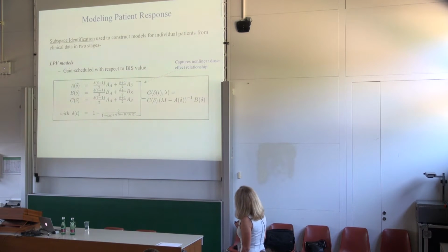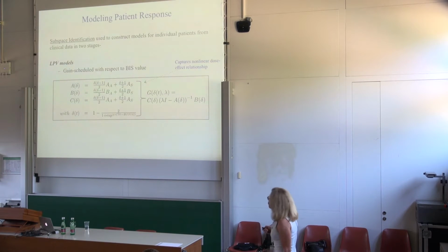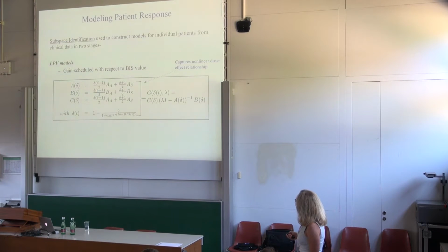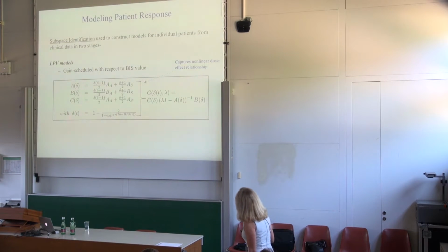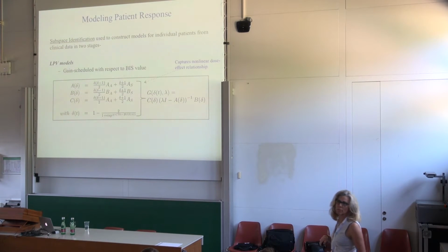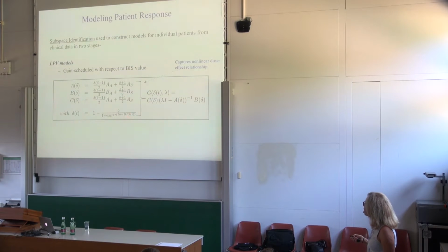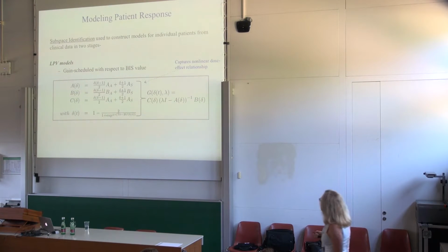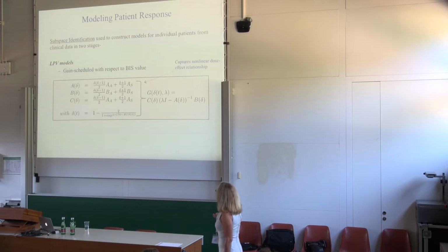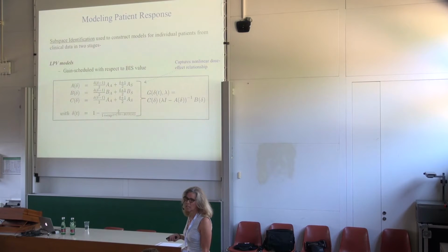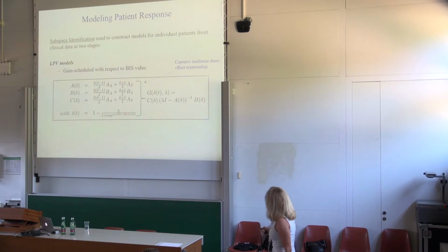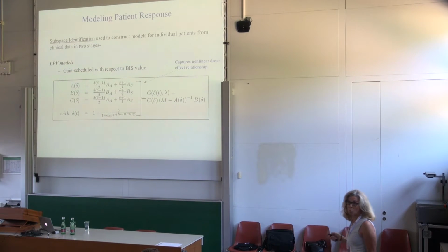And then we essentially developed a linear parameter varying model that smoothly transitioned from alert to sedated. So basically when delta is -1, we're fully alert, and when it's +1, we're fully sedated. This just smoothly transitions based on the BIS value itself. Okay, so this gave us these linear parameter varying models. These are, to be rigorously correct, quasi-LPV, because we're actually relying on a measured output.